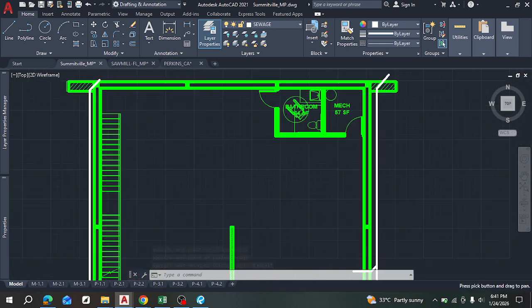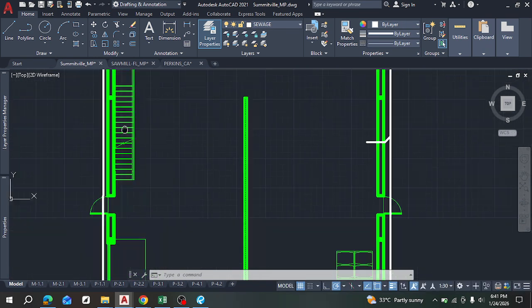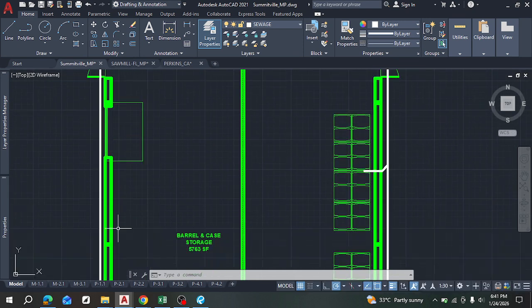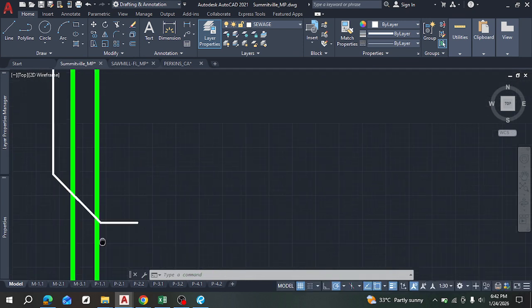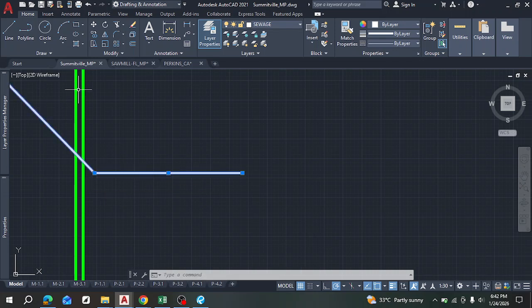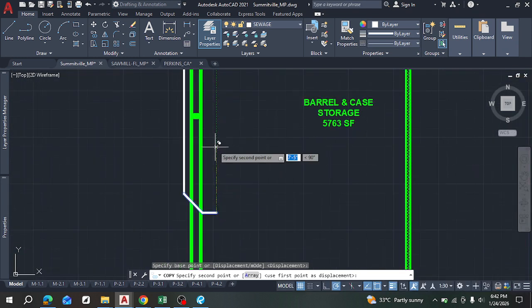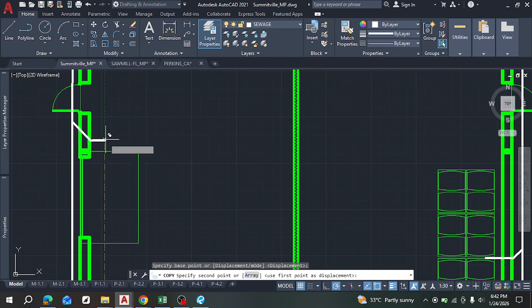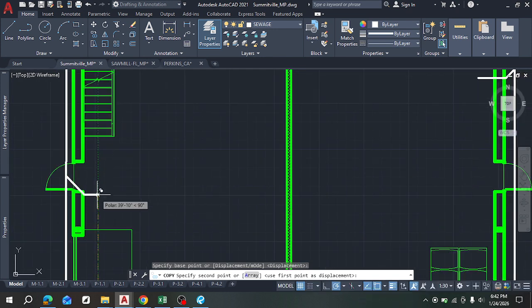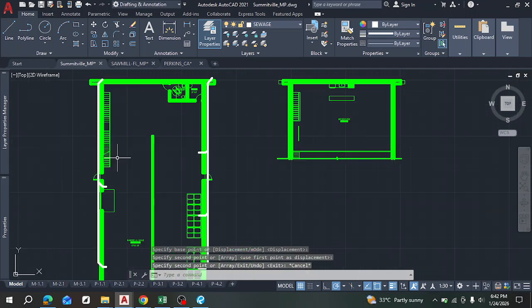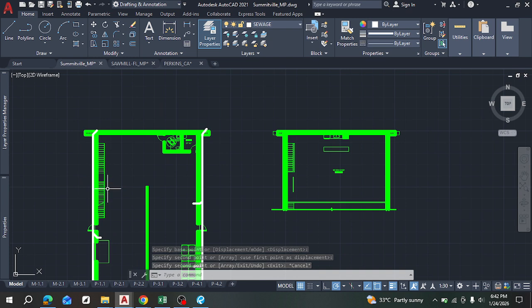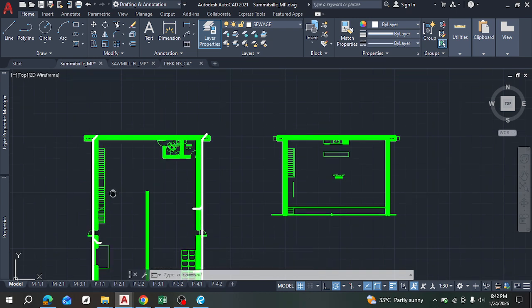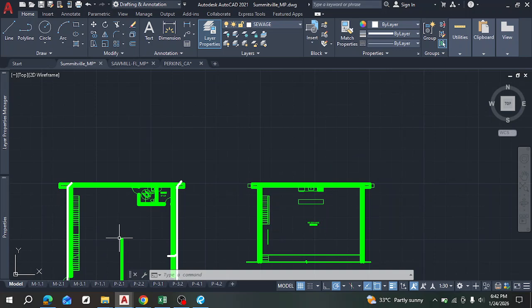If you have to make any discretionary, personal decision to make any changes, make sure you have a valid reason. My reason for wanting to run pipes outside the wall is because I don't want putting in a clean out to be a problem. But there are some cases where it may not be the best option. So it's good to have a valid reason, so that if that reason doesn't apply anymore, you can make your changes, right? So you don't just copy or cram what I'm doing, right?